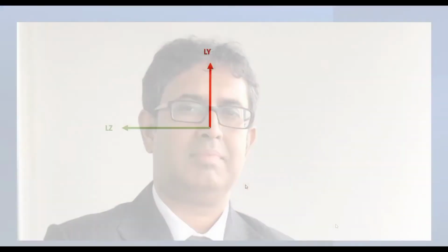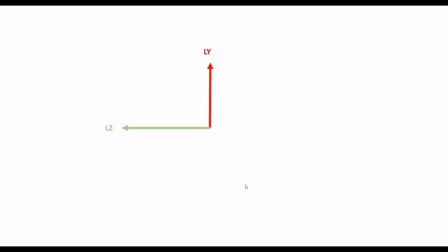We will start with the most common concrete section, the rectangular section. So what you see on the screen are the positive direction of the local y and local z of a member, depicted as Ly and Lz respectively. As you understand by now, the positive direction of the local x-axis is coming out of the screen towards you. Now, if a rectangular section is assigned to a member, the rectangular section will be oriented like this with respect to the Ly and Lz axis.